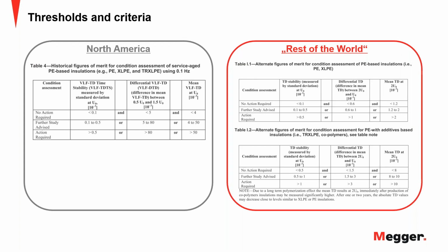All of these things have an effect influencing the tan delta. You have even external influences. The test is very sensitive. So even to get the values is already pretty challenging in the field. And then taking these values and trying to calculate a remaining life is not possible.